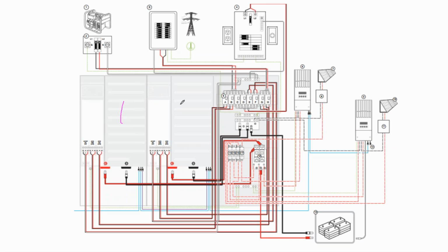So here's inverter 1 and here's inverter 2. And that can be kind of nice in the off-grid arena to have double stacked inverters, because if something goes wrong with one of them, the other one can function while the first one is offline.